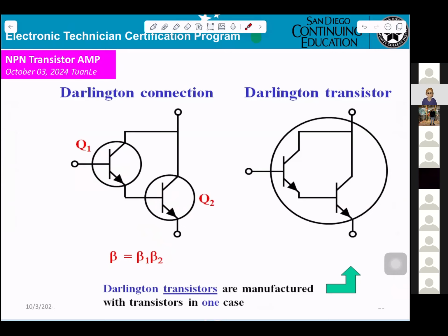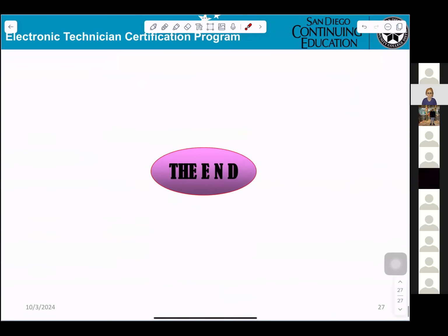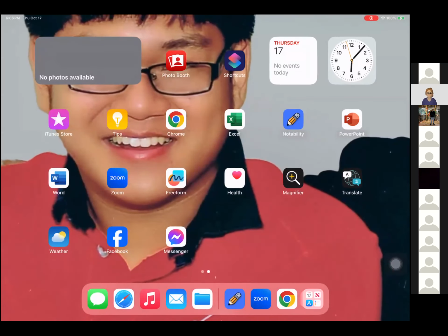That means you get a very big current. However, when you're working on this kind of circuitry, you have to be very careful. If you short the ground to the output here, they cook right away. They will be burned.